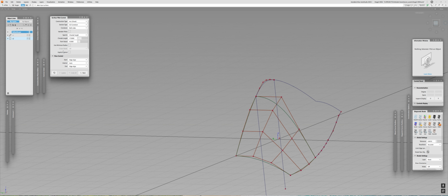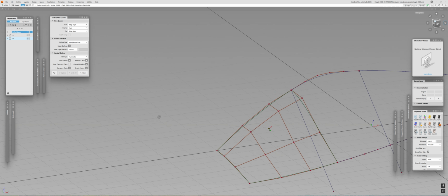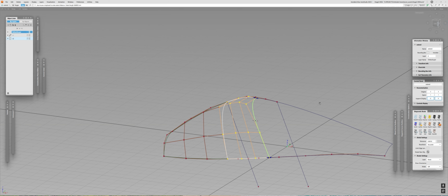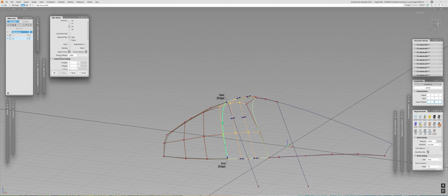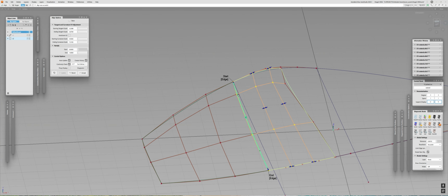And if I activate the surface fillet controls, just temporarily for the fillet tool, there are these options for the tangent scale. The distance between the first and the second CV row and the second and third rows, they call the tangent scale and curvature scale.